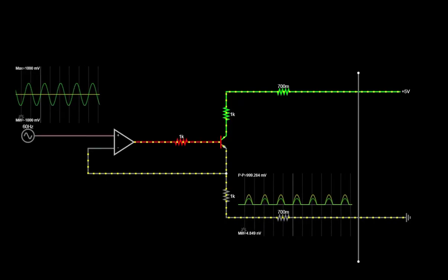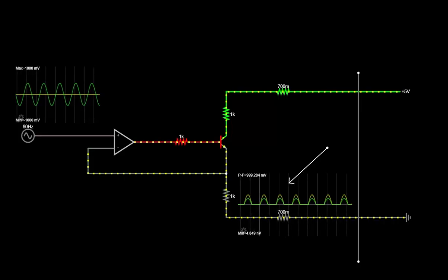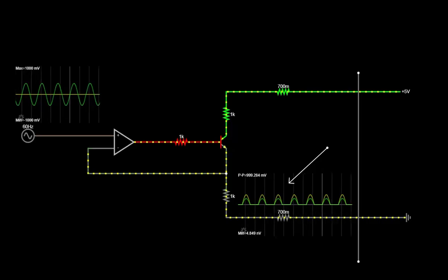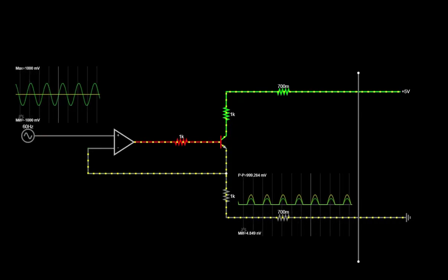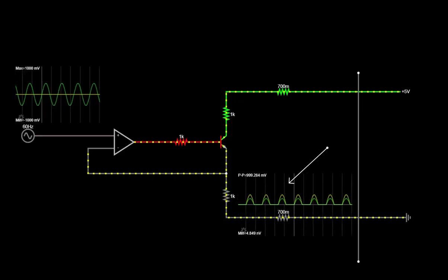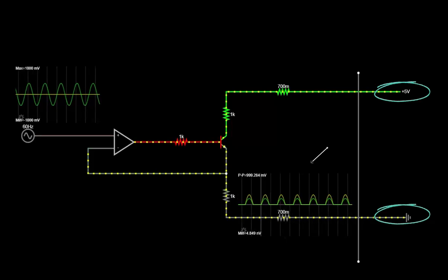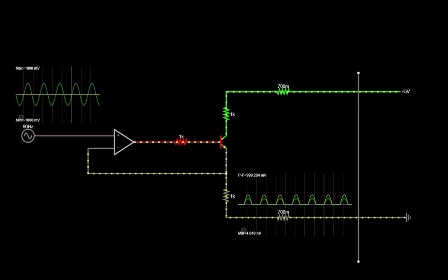You can now see that as we input our 1 volt amplitude sine wave, we get, well, something that looks sort of like what we're going for. There are two issues with this circuit. First issue is, since we're only using a single-sided supply, we can only handle positive swings from the waveform on the input. Thus, the negative half gets cut off when the negative cycle of the sine wave begins.